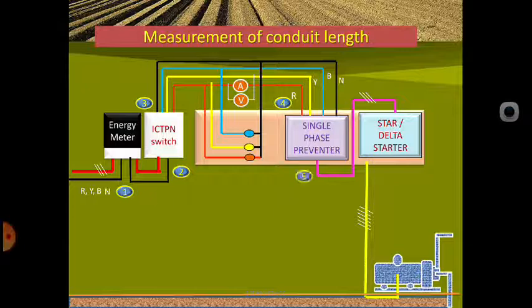Next, the fifth point we are using for another purpose. This is a 1 square mm cable for this purpose. What is the purpose? It is for pilot lamps and indicating lamps, if required. Otherwise you can take from 5 to 6.